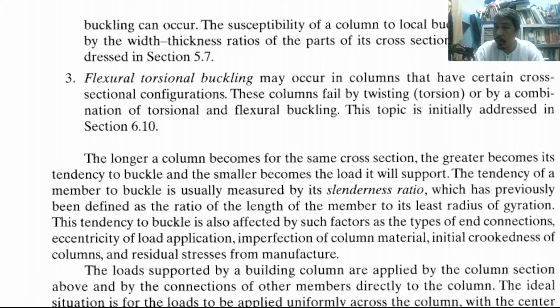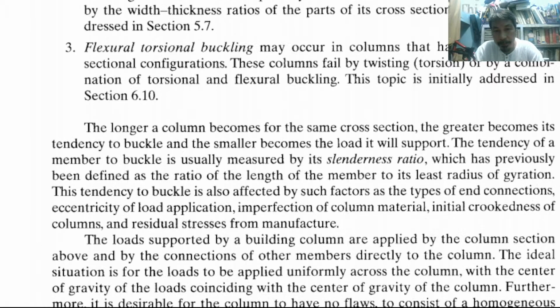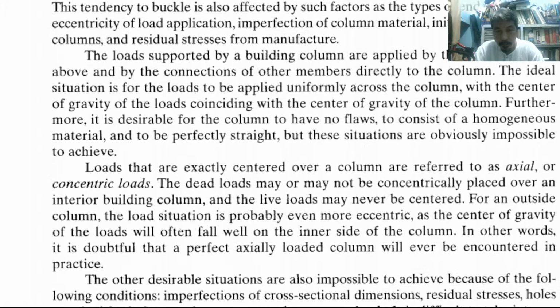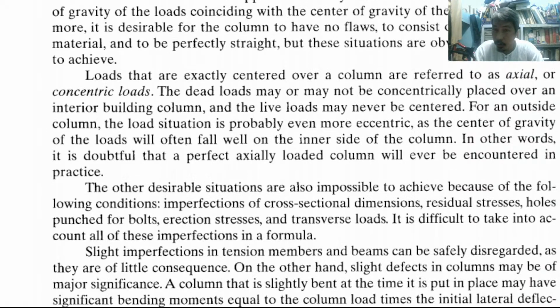For the Euler compressive force formula, we divide both sides by area, if you can still recall. And because there is a relationship between area, inertia, and radius of gyration, radius of gyration, let us review, is equal to the square root of inertia divided by area.